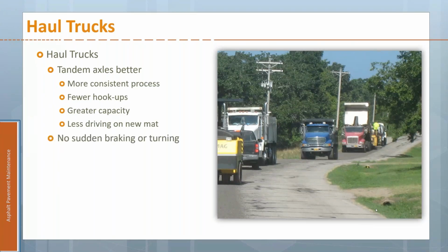Make sure, again, no sudden braking, no sudden turns. That's going to pull the aggregate out of that binder, and you'll have kind of an ugly spot there. So make sure your drivers are aware that that's how that needs to work. And then watch your truck tires as they're leaving the job site. Make sure that they're clean. They're not picking up any of your binder, or sand them if you need to keep anything from sticking.